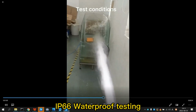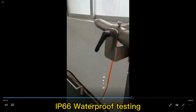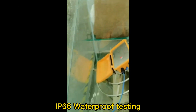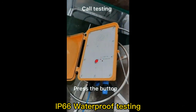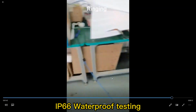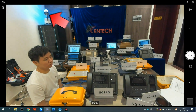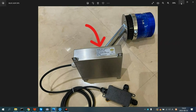At this time, the testing machine starts spraying water. The water spraying time per square meter of the shell surface is about 1 minute, and the test time is at least 3 minutes. After spraying water, we'll make a phone call to test that the call is normal. Test is now completed. The blue signal light is always on, and there is a sticker on the body to display the product serial number.